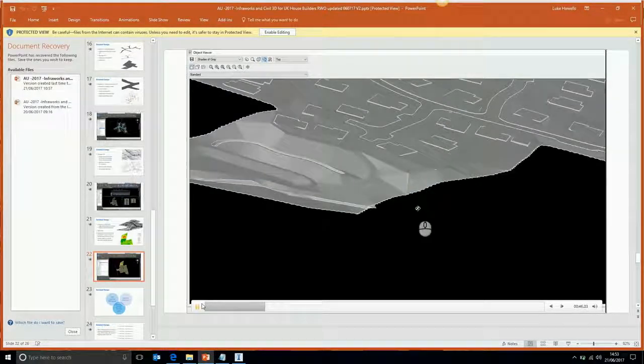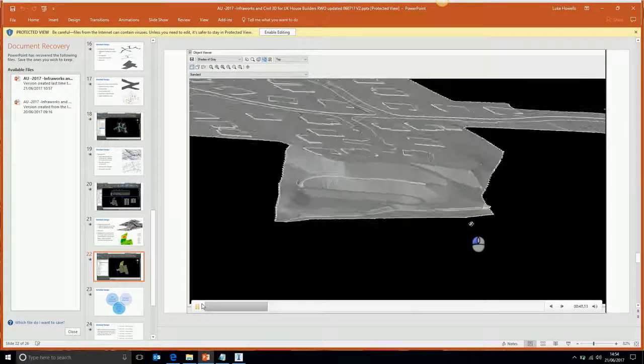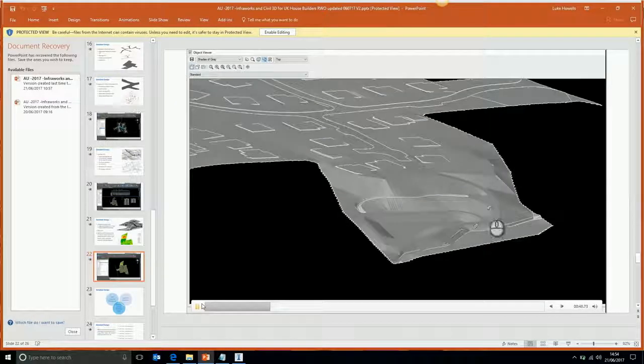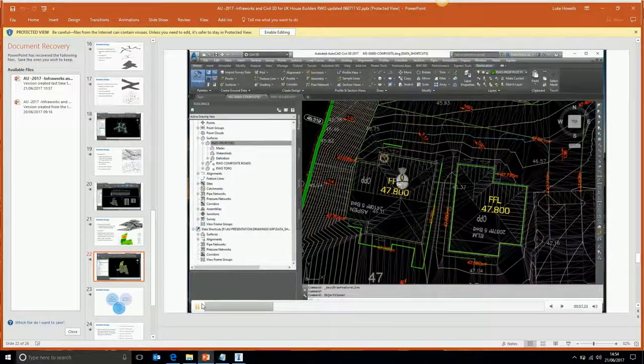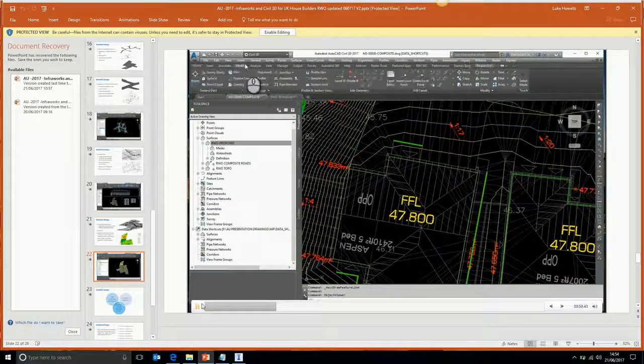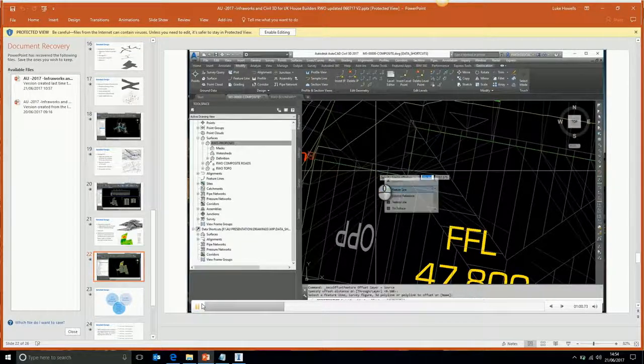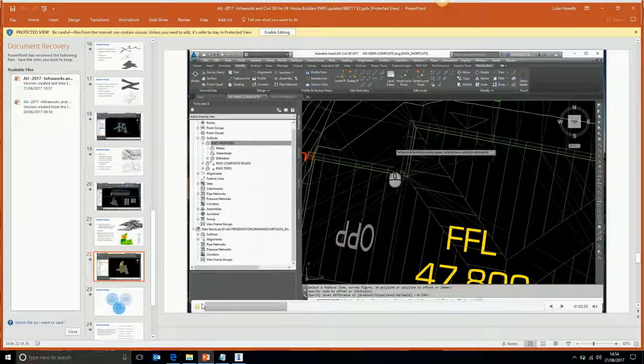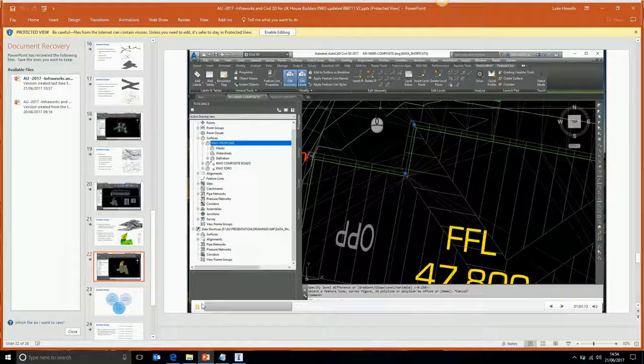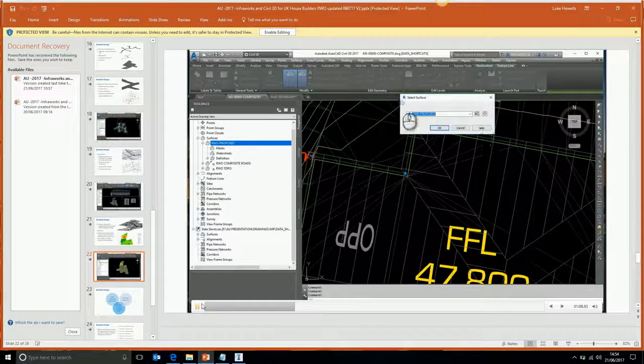They've got a 150 step down, which you would typically get around your plots, apart from the fronts, which have got level access. Apart from this plot here, which we're now going to build out, show you how we'll build that out a bit further. Just use standard offset tool in civils, take the feature line, offset at a distance, horizontally and vertically what we want, so that's your 150 step down. If we add that to the surface as a break line,